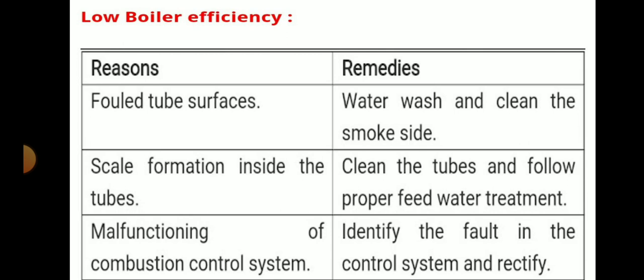Scale formation inside the tubes means clean the tubes and follow proper feed water treatment. You can remove scale by cleaning the tubes and following proper feed water treatment. Malfunctioning of the combustion control system means you can identify the fault in the control system and rectify it.